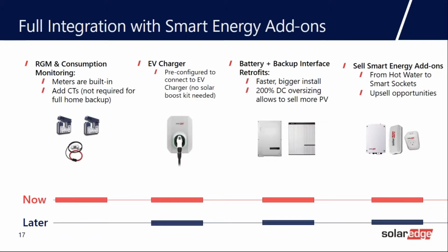The reason for this is many people did not want to have to put the inverter in the garage. They either wanted it outside where it was accessible, or maybe in the basement. So they wanted this remote standalone unit that they could run wires and conduit to, to transition between inside and outside or into a different location. So that's what that does.